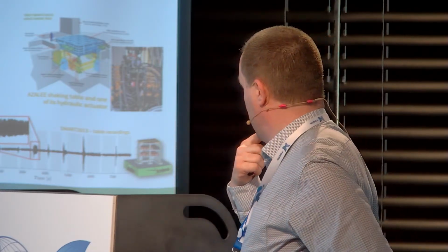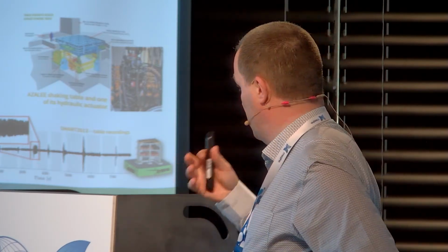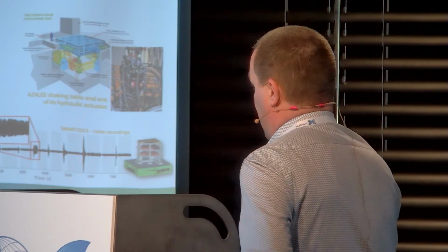And I just want to mention one which is quite interesting for me. That's one which was driven by CEA in France. The idea was to control the shaking table tests they have, because when they perform shaking table tests, they have a building on the table, which is going to be damaged. That changes the dynamics of the building, and that, of course, changes the control you have to apply, because the control is based on the first eigenfrequency of the system. And of course, if damage appears, that will change the eigenfrequency. So the goal was to catch how the building is going to be damaged in real time.